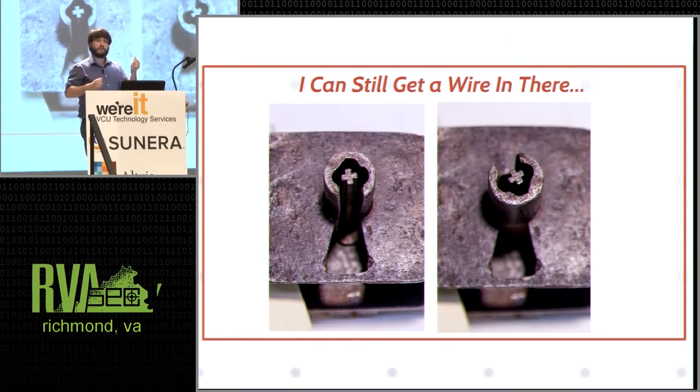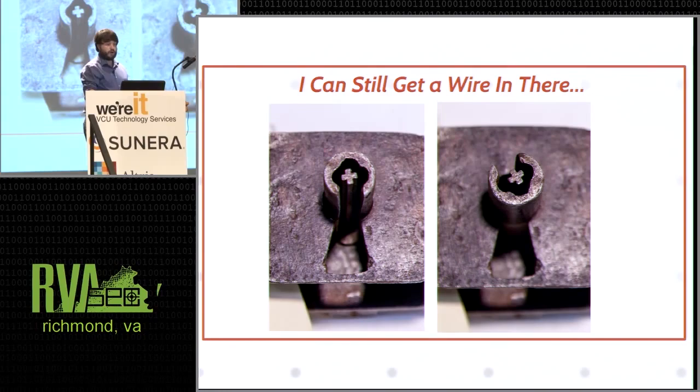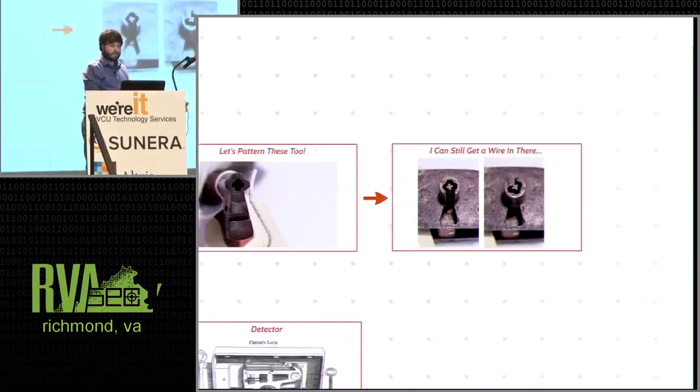And the curtain actually ends up being really important for lever locks as well, which we'll get to in a little bit. But the curtain covers your key, and then as you turn the key, it continues to cover the keyway. So if you're getting in there with a wire, as you begin turning, that whole thing will turn with you, whatever tools you're trying to use, and it just closes off important parts of the keyway from you. Curtains became much more elaborate with the lever locks and much more effective as well.